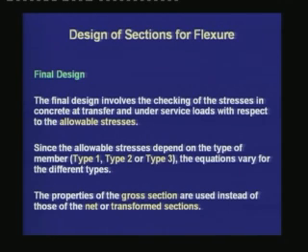Now, when we learn the equations, we shall use the properties of the gross section instead of the net or transformed sections for simplification of calculations. We had seen earlier in the analysis of members that if we use the more rigorous calculations based on the net or the transformed sections, we do not gain much accuracy over the calculations based on the cross section.